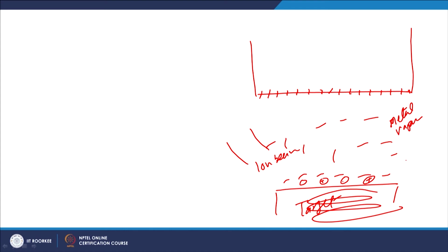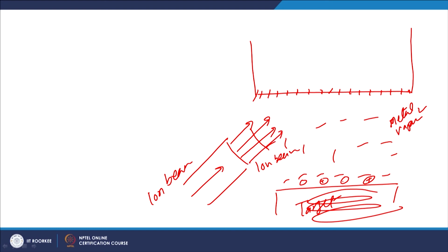So in order to increase the bonding, during the process of deposition, either by metal vapor deposition or sputtering or ion plating, we use an individual source of ion beam, and that is directed towards the surface of the substrate on which the material is being deposited through the various approaches, either through the metal vapors, or the sputtered ions and atoms, or the metal ions obtained through ionization of the metal vapors.